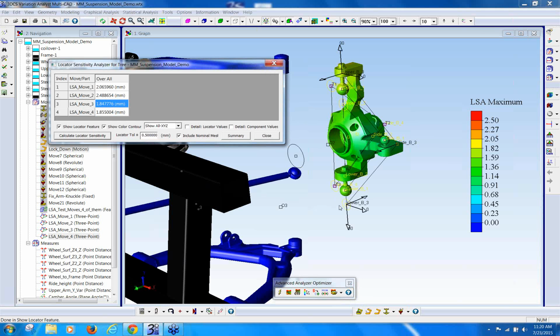So one of the things this is telling me is that the original design of a knuckle, where the ball joints are hovering straight above the axis, is a better design. This is the exact same location system as the original one, except a bigger spread. If I go down farther and up higher and farther out, I get the best results.